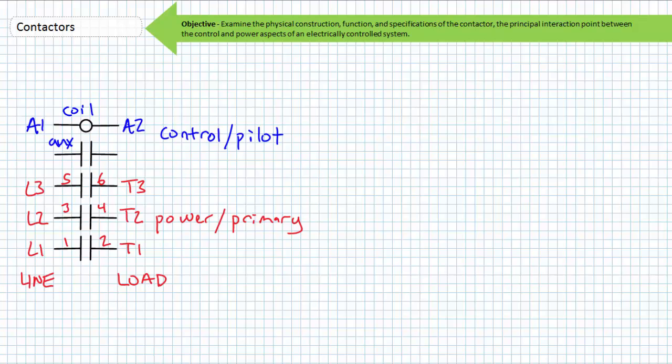the brain and the muscle, but also between the 3 independent high power contacts. L1 to T1 is a normally open switch, in no way, shape, or form electrically connected to the coil. The only link between the coil and any of the high power L2 T2 contacts is a physical one, in that when the armature is pulled into the coil, these pairs close.